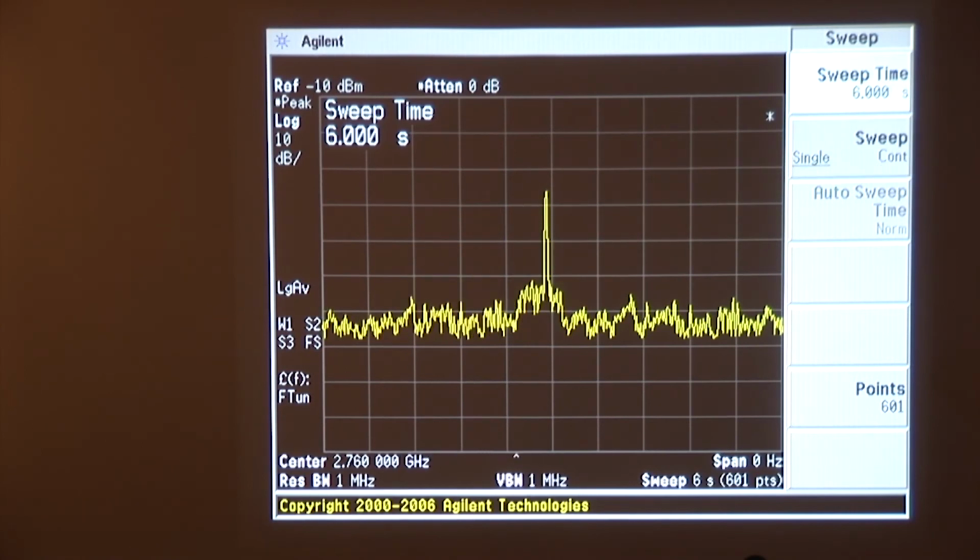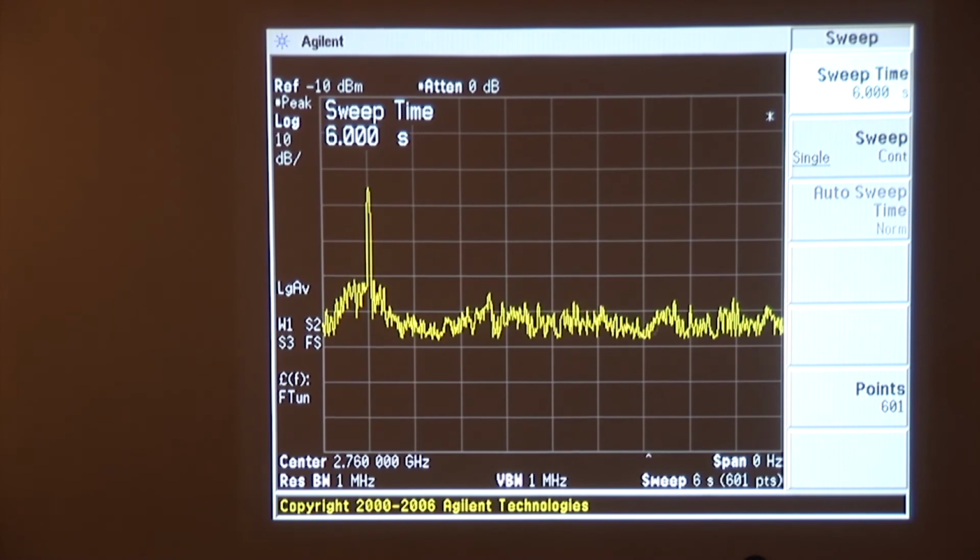And then I'm going to hit the single button and start the traces. And I watch to see what happens in the first interval. And I wait until I get the radar to hit me right in that first interval. There. Now we're going to get one complete rotation on the radar. Boom. Beautiful. The radar looked in our direction, some time elapsed and looked in our direction again.